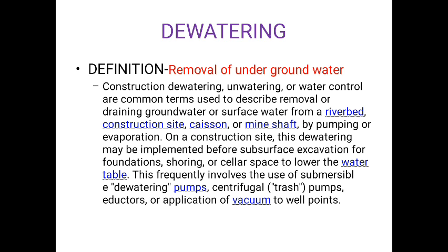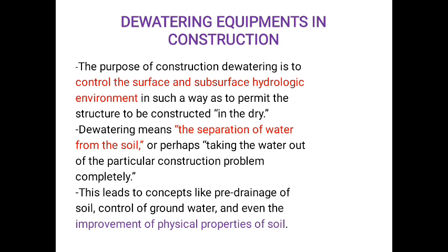On a construction site, dewatering may be implemented before subsurface excavation for foundations, shoring or cellar space to lower the water table. This frequently involves the use of submersible dewatering pumps, centrifugal pumps, eductors or application of a vacuum to well points. Dewatering equipment in construction.